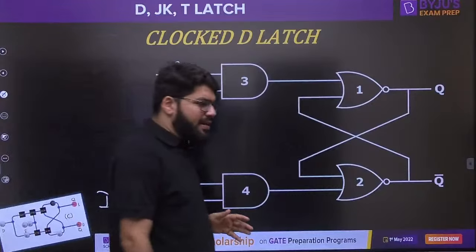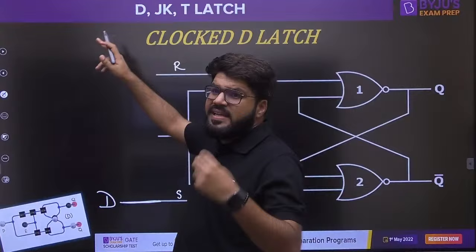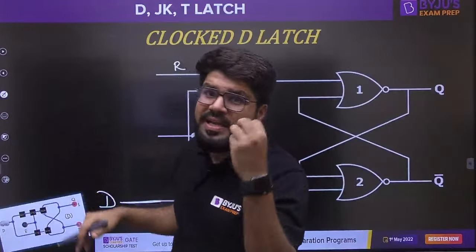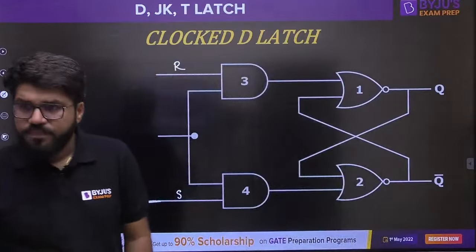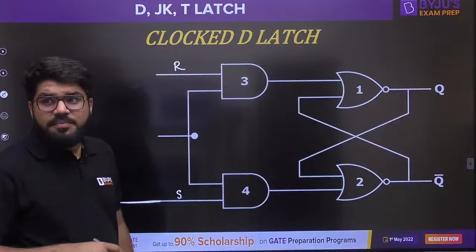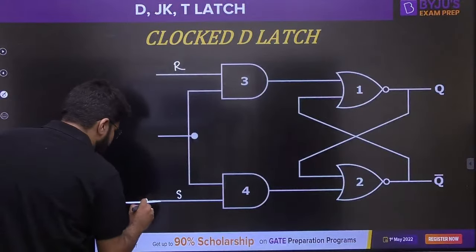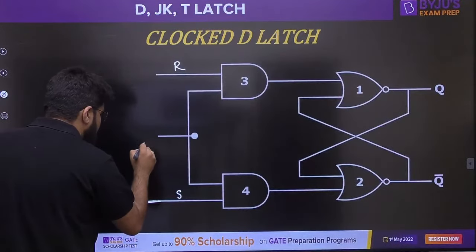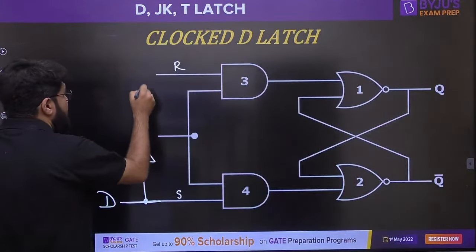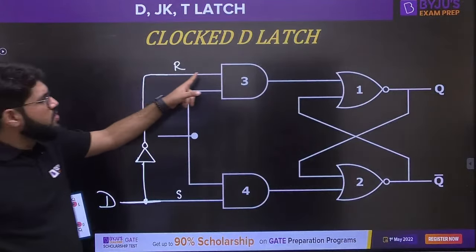What I want to ask you right now is, can you mention what D actually stands for in the D latch? Okay, so now I'll tell you the connection. Just name the S input as D. Take another connection from here, invert it and put it into the R. The complement of D goes into the R input.